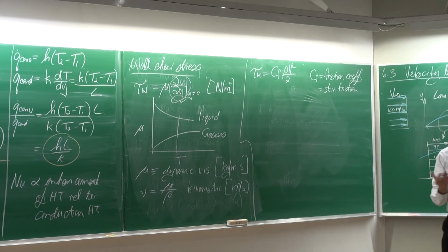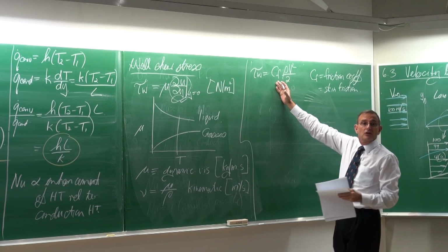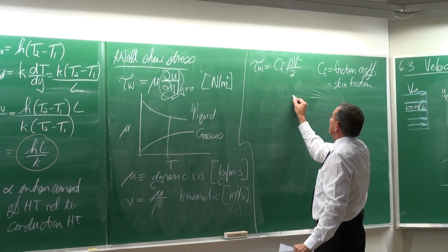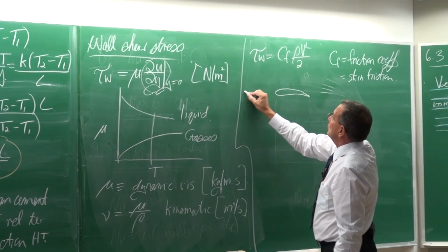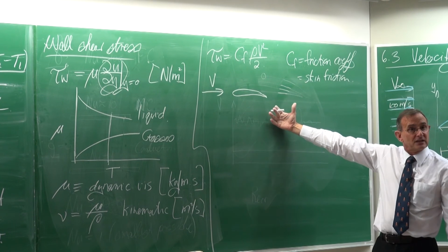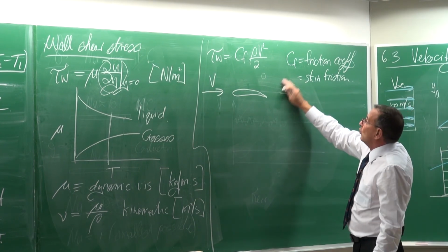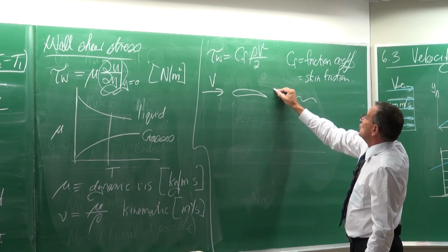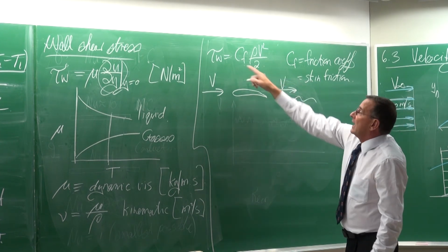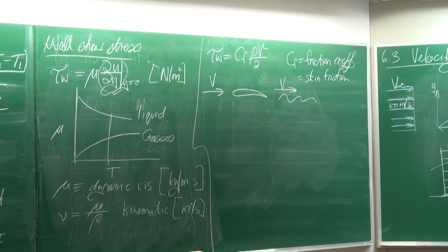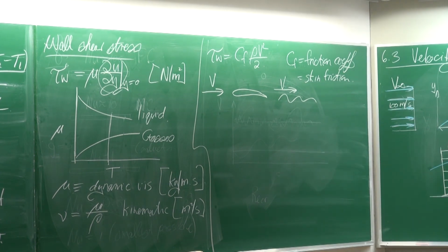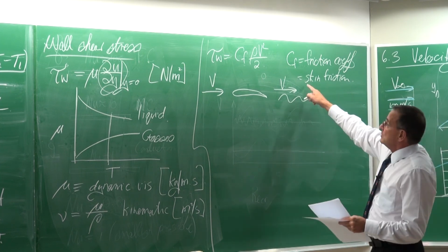And this skin friction coefficient can be determined for any body. And if we do it typically for an aeroplane, we would typically maybe use the free stream velocity for that specific geometry, or if it is for another type of geometry like that, then we would use that velocity and determine that, but it would be related to a specific geometry. Why is that important?